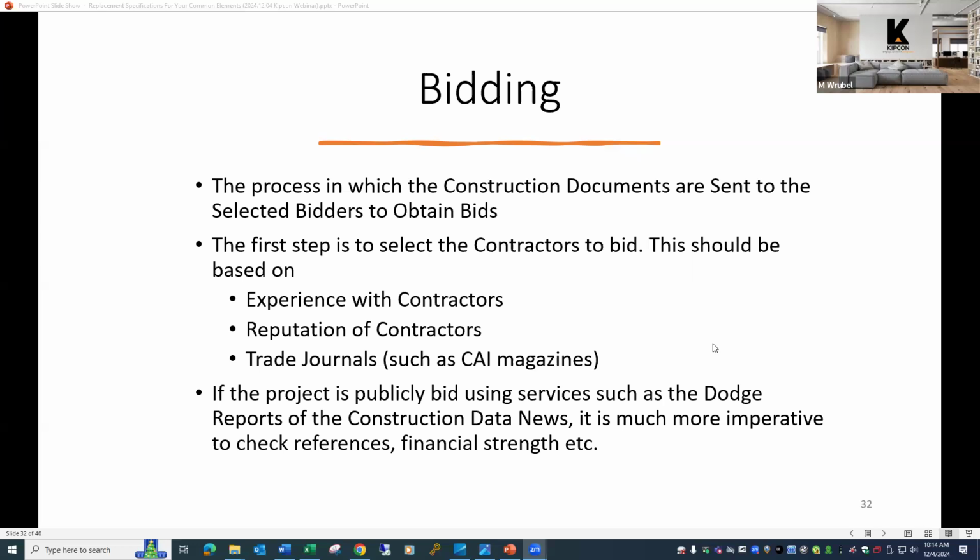Say, for example, mobilization costs. You can look in the summary, and you could see what each contractor is charging for mobilization, or for traffic control, or for milling, or for installation of speed humps. You can compare and look across. You can also look at duration of project. Sometimes a contractor may have a great price, but you look at the duration of the project and it is much longer than the other contractors. So the summary gives an idea of what types of questions you want to ask of the contractors.